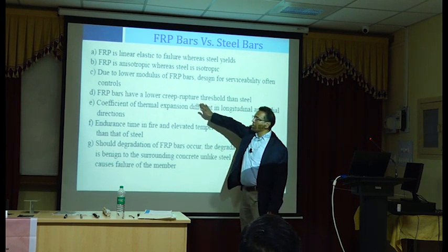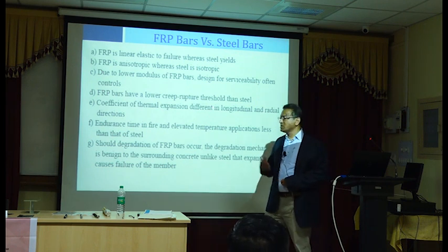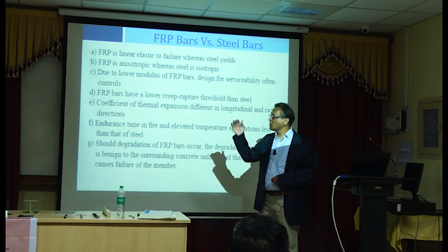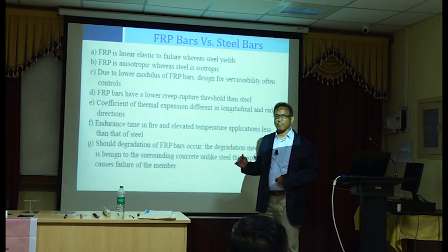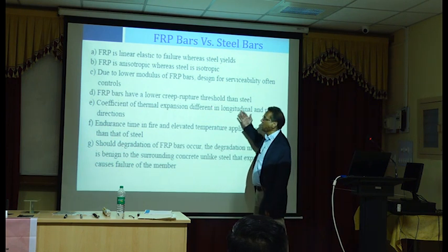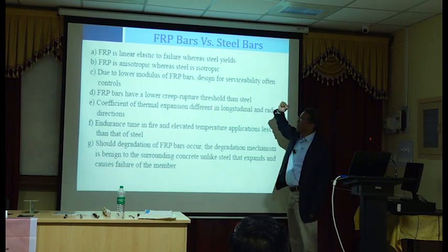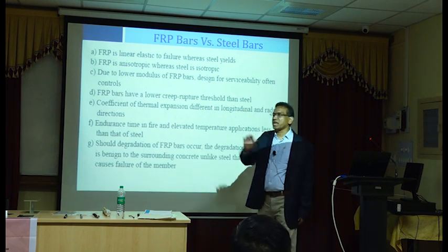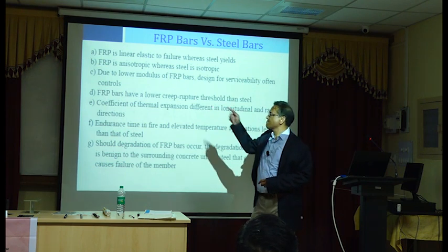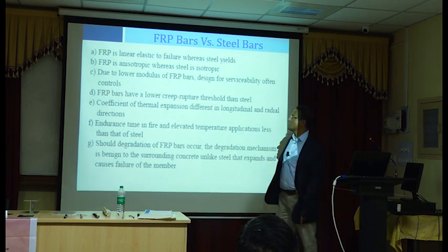So that kind of stuff is very hard to design. All you have to do is add more FRP bars, but if you add more FRP bars to bring down the stress in the bar, you are losing the benefit of high strength. If you ask me what is the most critical design item in practical structural design, creep rupture is a problem. Everything else you can handle other than creep rupture.